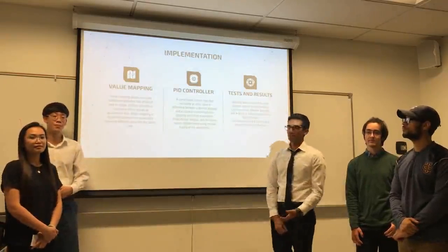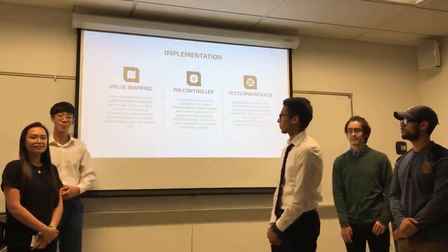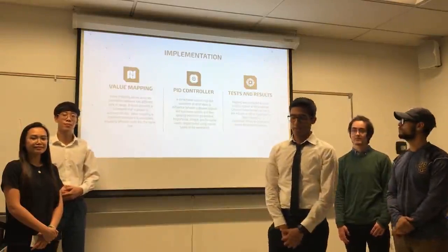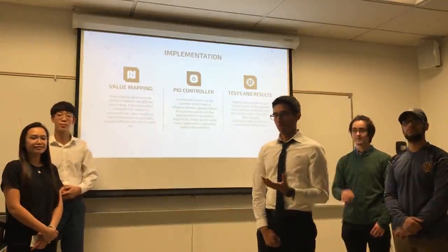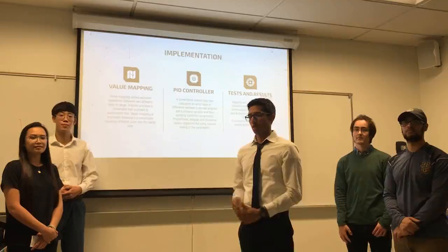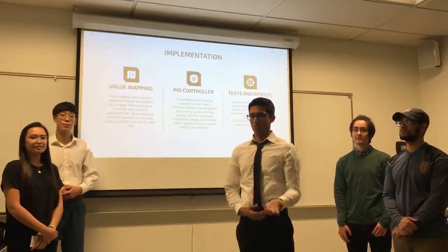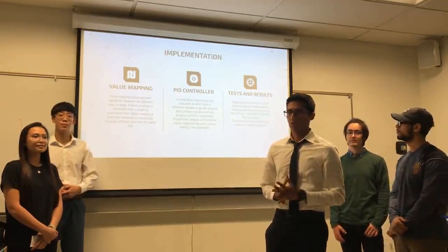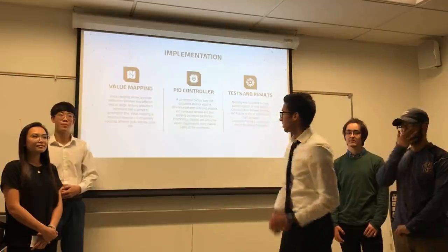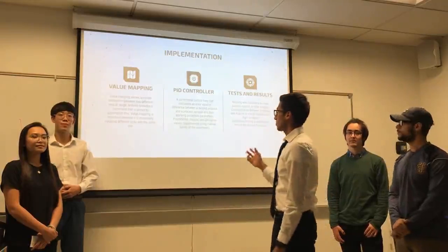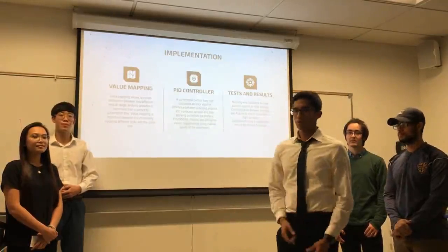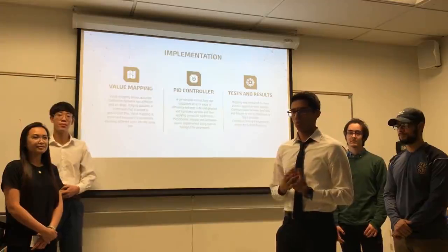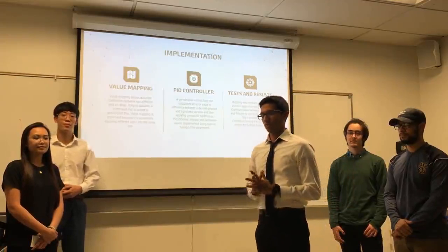So in order to begin our testing with our project, we had to develop some scripts that involve some value mapping. Our 10-bit binary numbers, for example, 0 to 1023, to 8-bit binary numbers, 0 to 255, in order to utilize certain functions within the Arduino program. Also, it was essential to use a proportional integral derivative controller to have better stabilization in the chair and a much more smooth movement for the user.